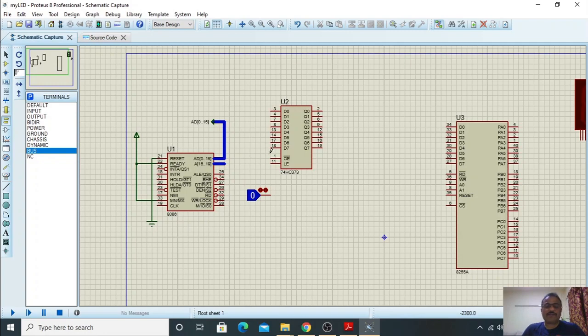Now, as per the circuit, this also has to be connected to the data bus. So once again click on the bus, place one bus terminal, drag it like this, drag it till here. Double click. Proper double click is required, otherwise this thing will come. You can press escape, double click and escape.